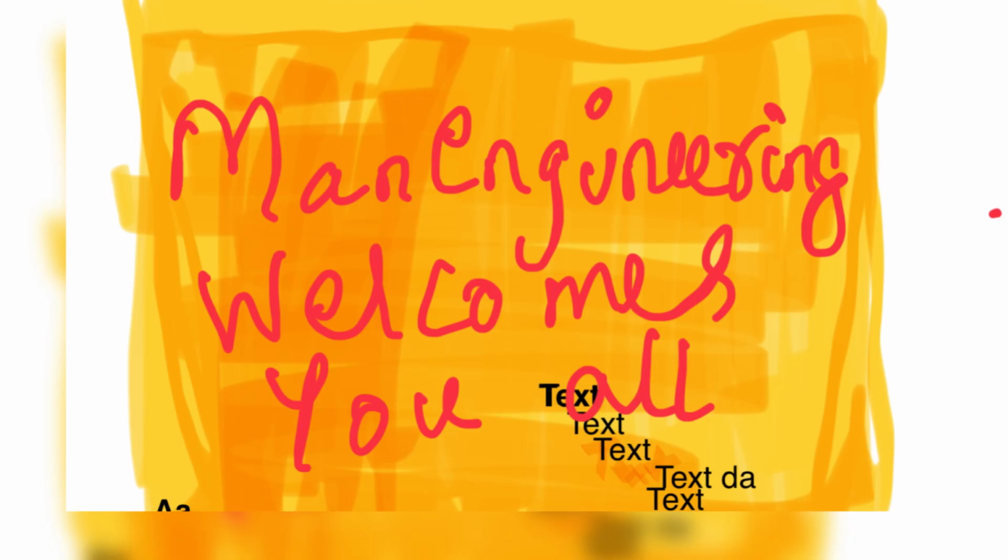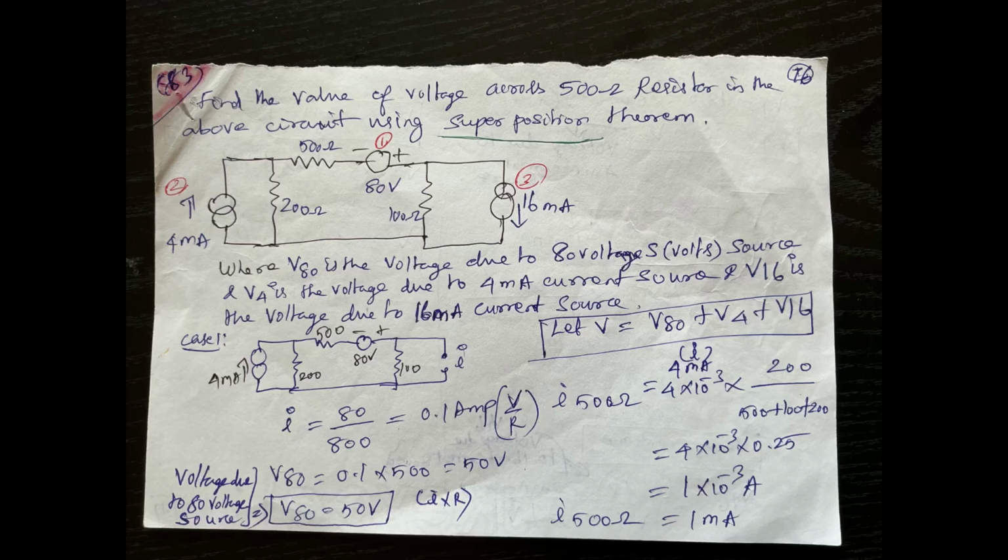Circuit analysis, or electrical circuit analysis, or circuit theory subject. In this class, we see the superposition theorem in different model circuits. In this circuit, splitting sources, output is calculated. The superposition theorem states that the output response produced by a number of sources simultaneously is simply equal to the sum of the responses produced by each of the sources acting separately.